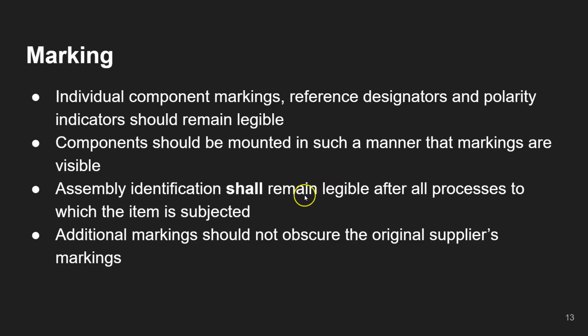Marking should not be placed on surfaces covered with melting metals or opaque coating. And if you're using etched marking, then you have to make sure that it is done carefully, because it may affect the electrical characteristics such as capacitance on the PCB.